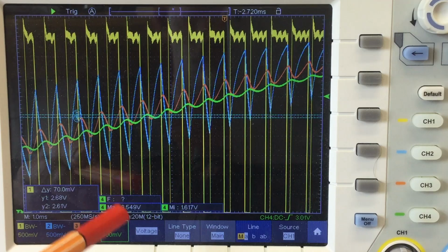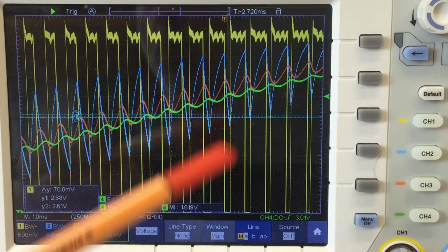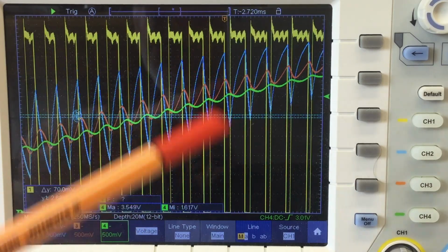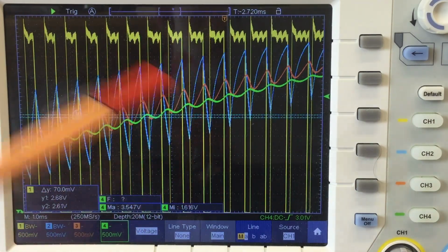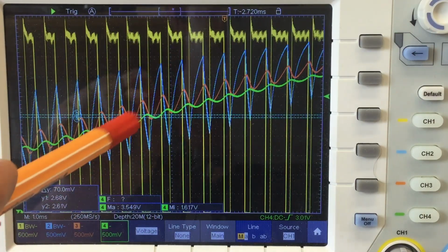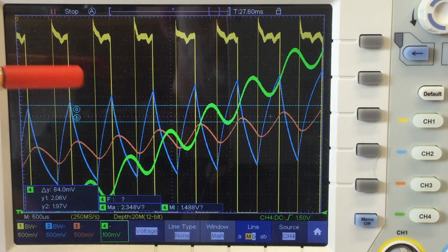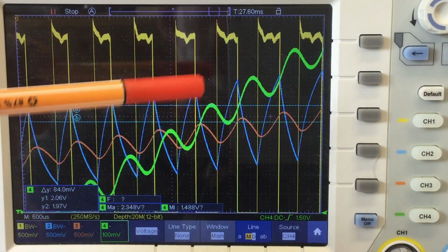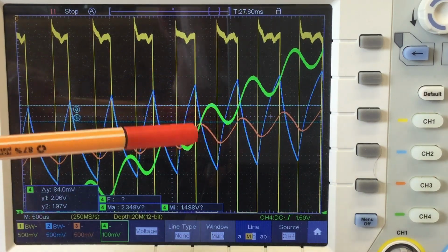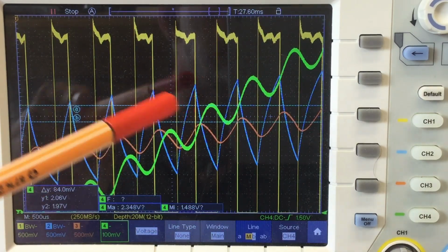Well, 4.4 volts divided by 70 millivolts is 0.016. Our design goal was 0.00391. So we are about a factor 4 off our design goal. But let's try to get a better measurement. Give me some time. Nope. Zooming in even worsened the situation, getting my accuracy. I'm measuring now 84 millivolts ripple here left, and we were aiming for about-ish 17 millivolts.